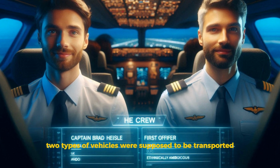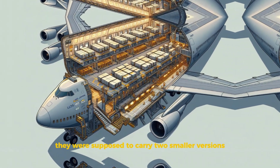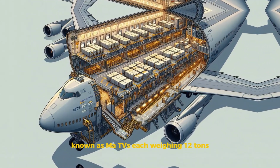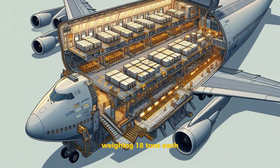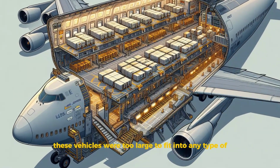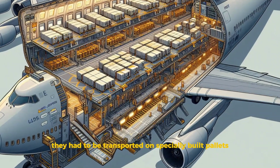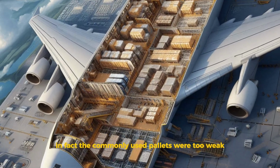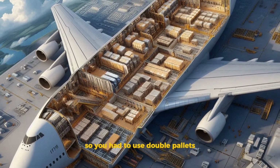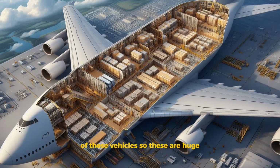2 types of vehicles were supposed to be transported. They were supposed to carry 2 smaller versions known as MATVs, each weighing 12 tons, and 3 massive Cougar vehicles weighing 18 tons each. These vehicles were too large to fit into any type of ULD, so they had to be transported on specially built pallets. In fact, the commonly used pallets were too weak, so you had to use double pallets with some plywood in between to spread the weight of these vehicles.